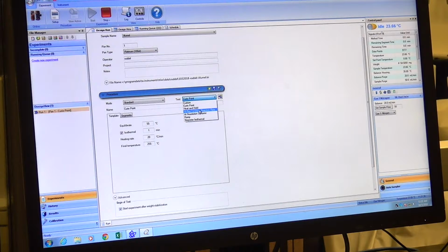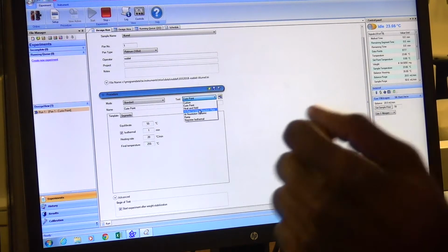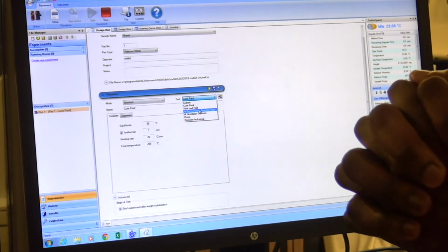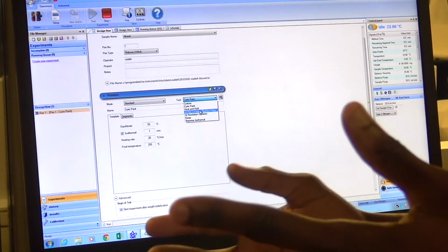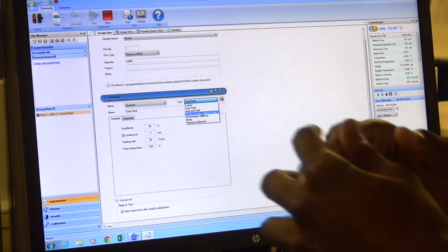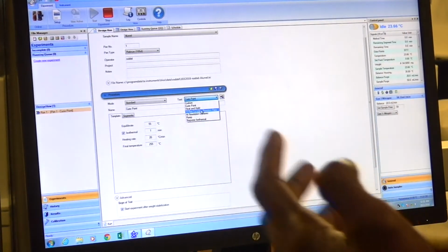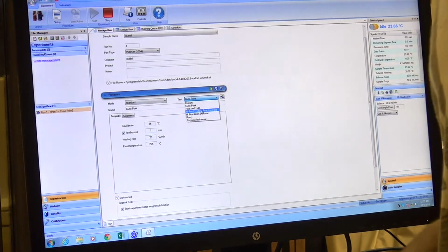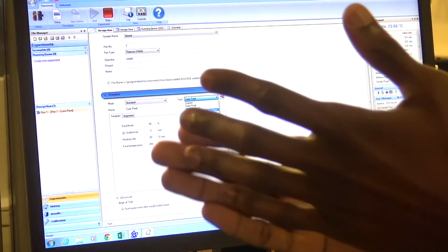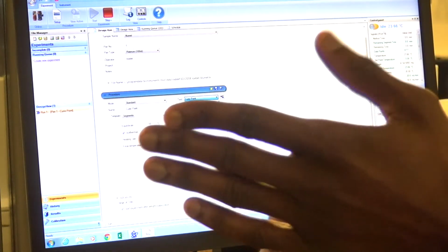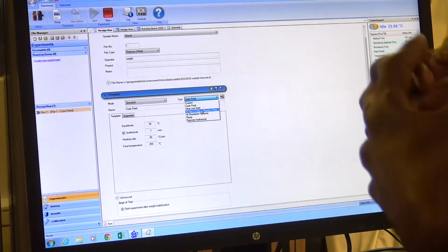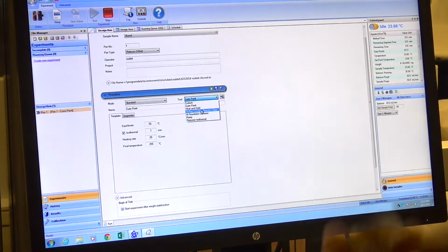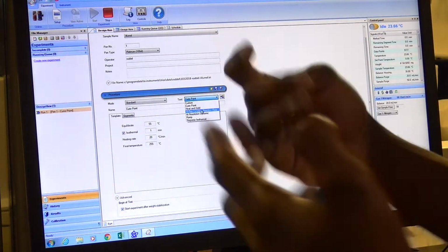This is a very interesting experiment in itself, where if you would like to better separate different degradation steps or different degradation events, one of the ways that you can do it is simply by slowing down your ramp rate, right? Because then you allow more time for things to happen at specific temperatures than you would if you were going faster. Now, that also costs you a lot of time, because the slower the heating rate, the longer your experiment